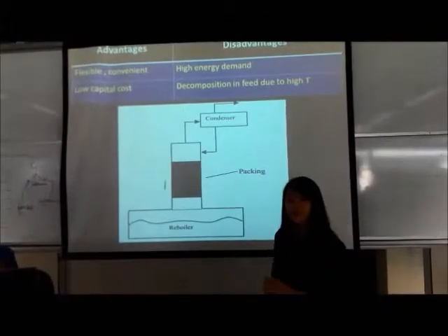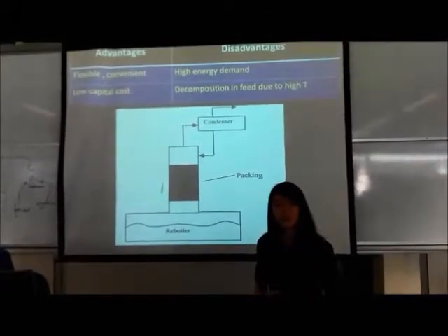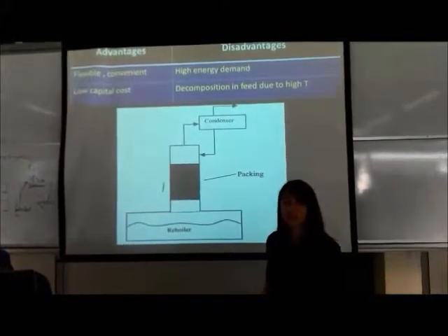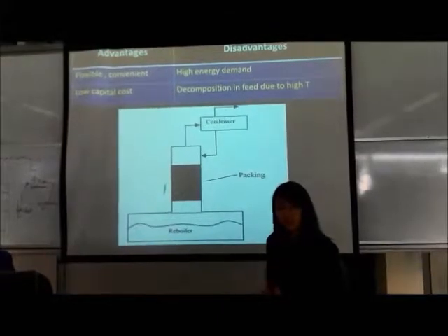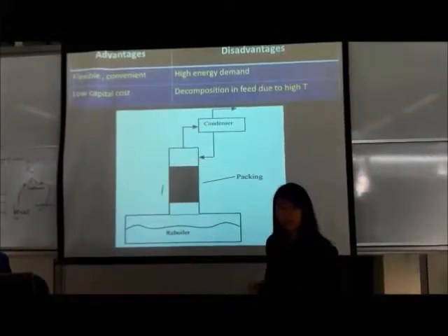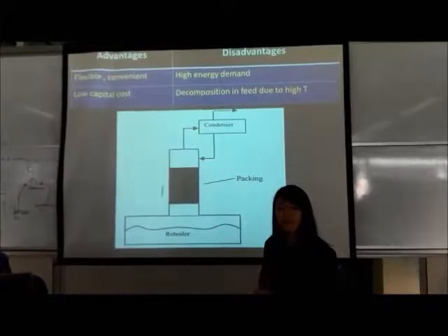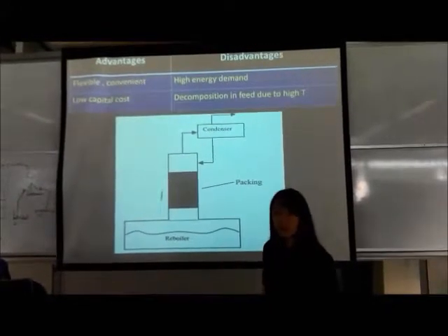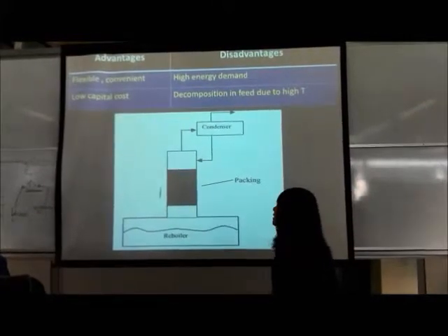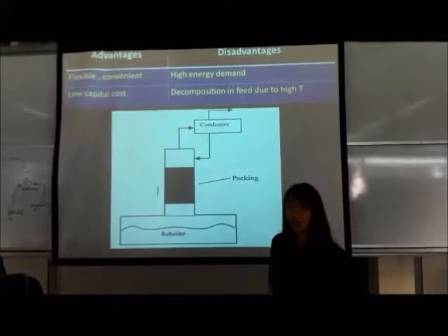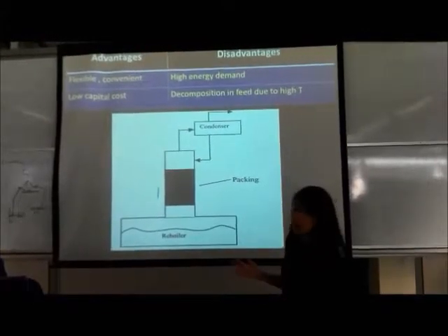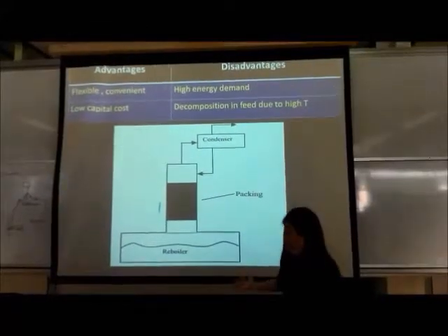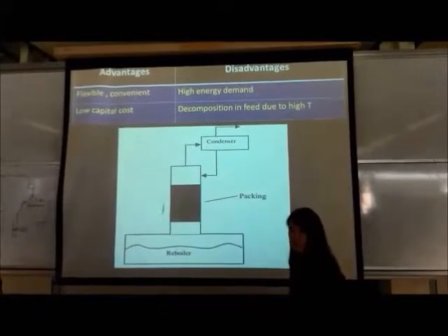There are a few advantages and disadvantages of batch packed distillation. The advantages are that it is flexible and convenient, as it allows us to deal with unknowns in the feed stream or the product specification, and it requires low capital cost. But the drawbacks are the high energy demand, and due to the high temperature, decomposition will occur in the feed stream.